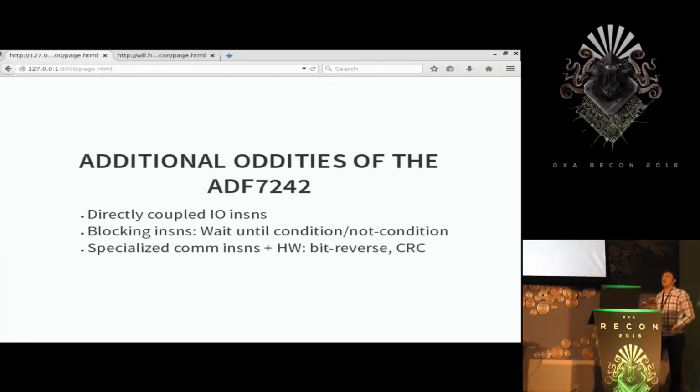And ironically, because of the way that's built and it's encoded, you can actually block the core until any condition bit is set. So you can actually do block until not 0, which is not an operand you ever find in the disassembled binary because it's not terribly useful. Once the core is halted, waiting for it to become non-zero, nothing's ever going to make it non-zero.